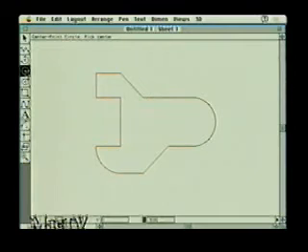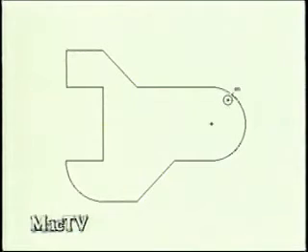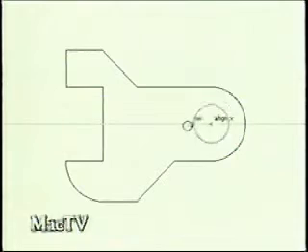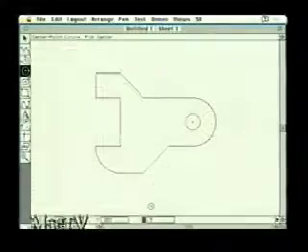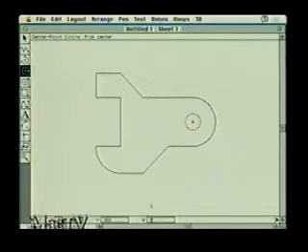Another example of the Drafting Assistant is using the Smart Cursor to do a circle. I can bring my circle in here, and to make a circle that's exactly centered, the Drafting Assistant will wake up the center for me. I can go right to that center and pull a circle right on that point. You might notice that this circle down here has a diameter of 0.5 right now. Well, I might know it has to be 0.892 for whatever reason, and when I hit the Enter key, it resizes exactly as I've entered. As well as the XY, so we have our own variables, whatever we want to choose for those. Yes, you have the ability to do total numerical entry.